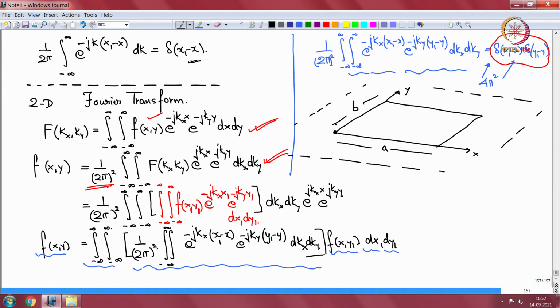Then there are individual modes on the panel. So in this direction the mode number is M, in the y direction the mode number is N. So the modal wave number kpx in the x direction for the plate or panel is m pi by a. Similarly, the modal wave number in the y direction is n pi by b.